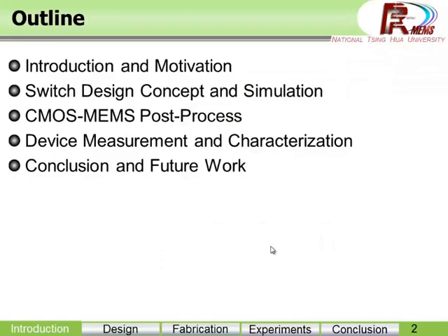To give a brief outline, I will start with the major motivation behind this work with circuit and MEMS integration, and to realize a low-actuation voltage design switch, I will introduce the working principle of the switch structure used in this work, followed by theoretical and finite element simulation. I'll then implement such a switch via CMOS-MEMS technologies.